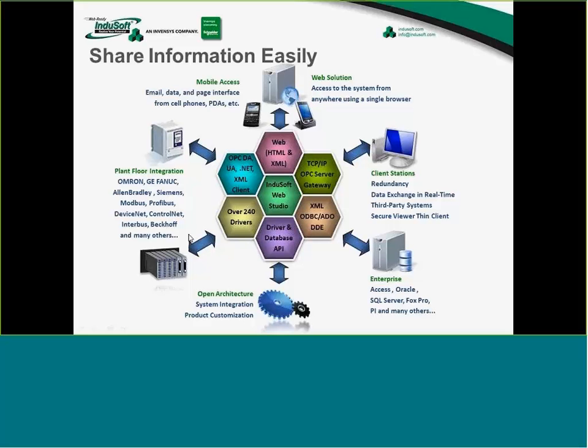There are licenses within InduSoft Web Studio that support multiple drivers. Let's say you have three drivers, and BacNet is one of those, Modbus is another, and Allen Bradley Ethernet IP might be a third. You can share information through InduSoft Web Studio from any driver to any other driver, and this allows you to share information between dissimilar company products. So you can get information from a BacNet controller to a PLC or vice versa.